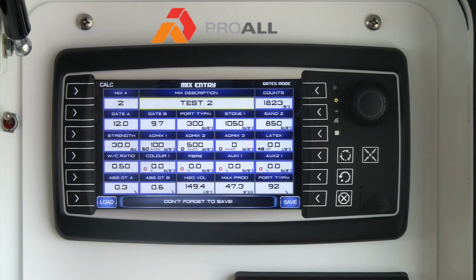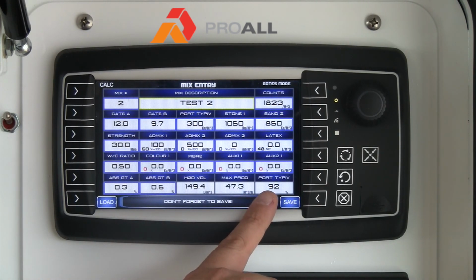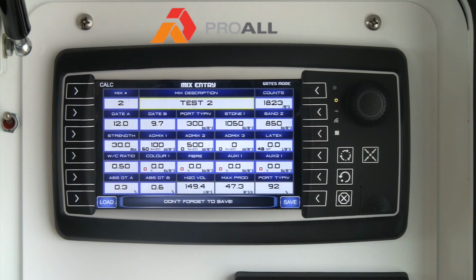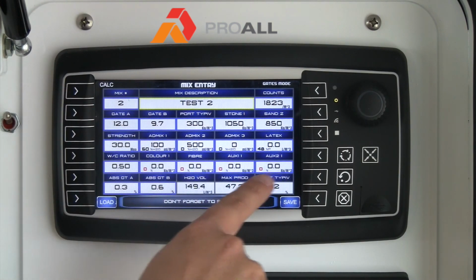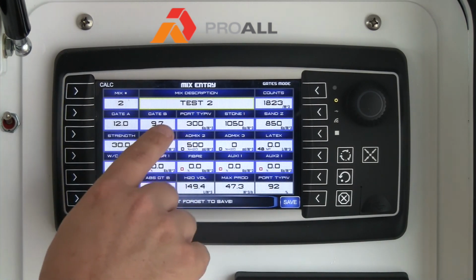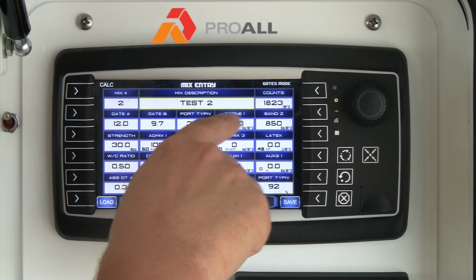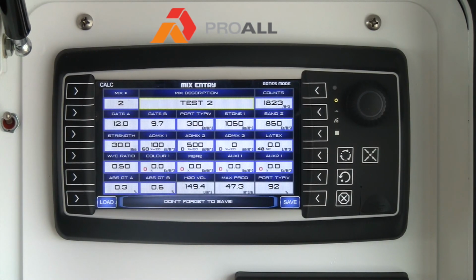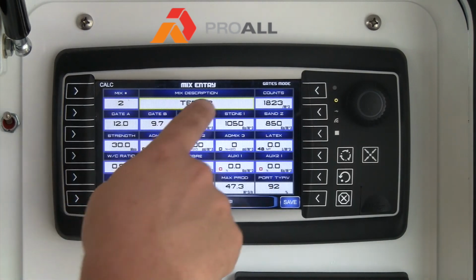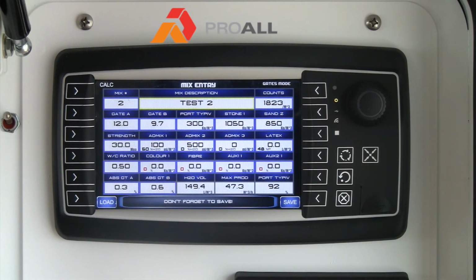We're going to talk about cement ratio, and that'll explain a little bit more what this value is here on the bottom right. So if you remember before, we picked Portland type 4, so you notice when I press calculate, it changed that to Portland type 4, and it also changed this to Stone 1 and Sand Z. So whenever you press calculate and you notice that those materials are the ones that you've selected in the calibration screen, then you know that it's using the proper values when it does its calculations. So in this case, again, Portland type 4, Stone 1, and Sand Z, and it's basically ready to go.